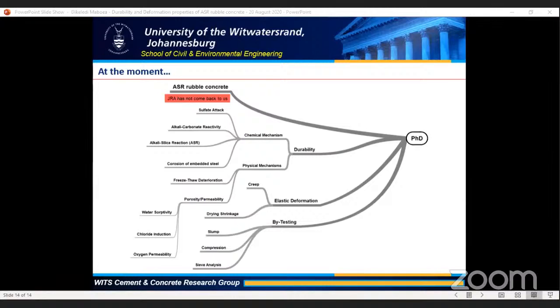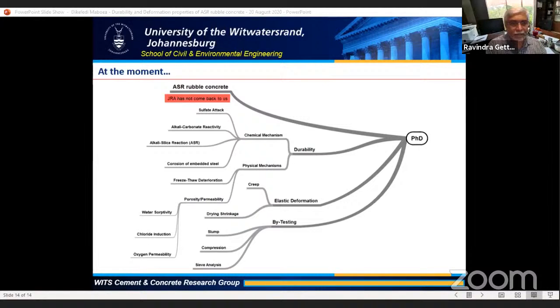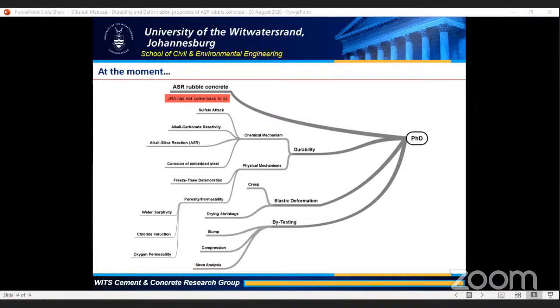But I'm thinking either adding something or making sure that what we are mixing our ASR affected aggregate with is not going to be as reactive.